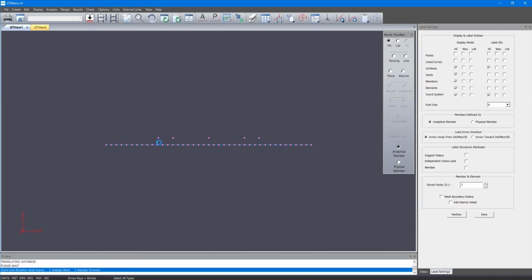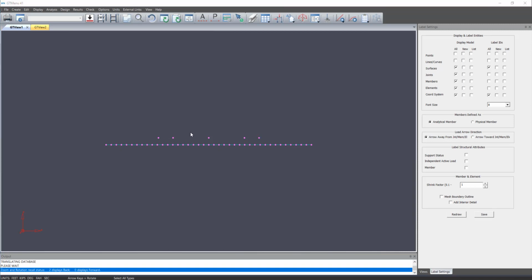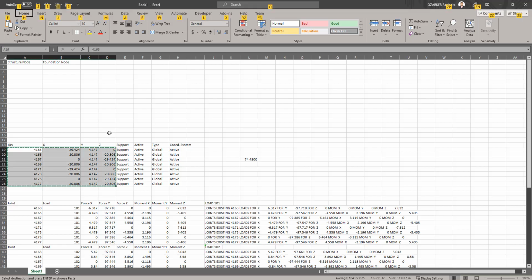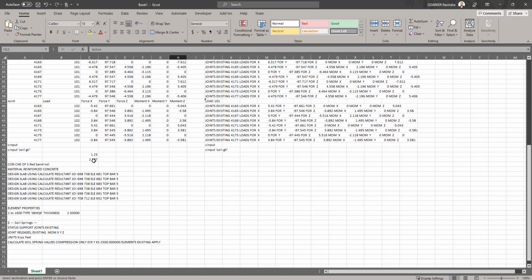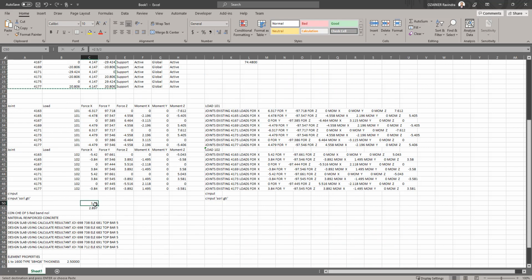And there's the file. Okay, so here, this is giving you the elevation view. You see this is the mat, and these are the nodes for the tank. Now, the reason why they're up in the air is because if you look at the coordinates that the structural engineer has given us for the base plate, it's at 4 feet. The mat is about 2.5 foot thick, right? So really, the height of the pedestal would be that distance minus half of the depth of the slab, and that should be 2.897. Okay, so let's draw those pedestals here.